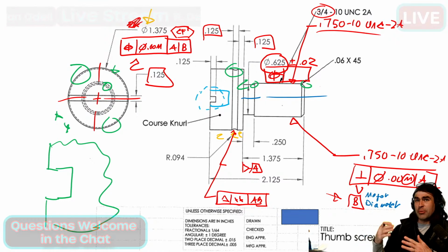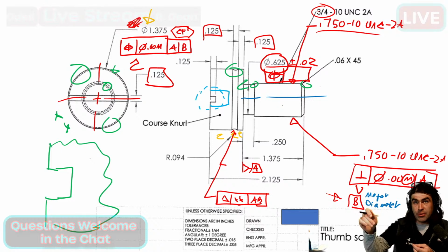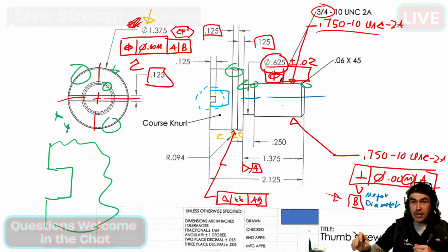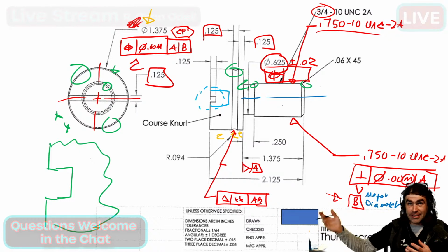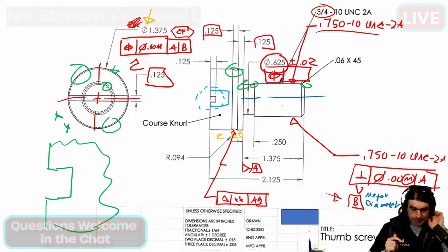What a CAD program should do is if you're going to use hidden lines on views on one sheet, they should be in every single view. That's not how it works, because typically CAD programs default to not having tangent lines or hidden lines. So you got to go in there and turn them on, right? So you might have one view with them, and then a view projected from it doesn't have them, and then chaos ensues, right?